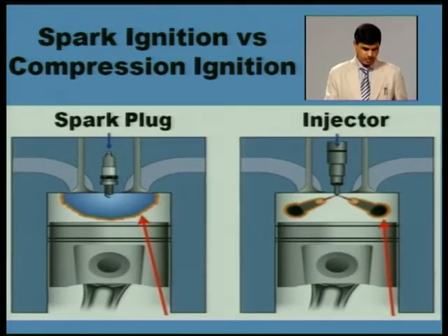In the case of petrol engine, compression ratio starts from say 8.5, even it can reach up to 15. But in the case of diesel engine, it starts from 15 itself. So the lowest compression ratio normally which we are getting in the engine is around 15. But maximum compression ratios these days in some of the vehicles, it is even 25. So here compression ratios are quite high. Higher compression ratio means during compression stroke, when piston will be reaching TDC, the clearance volume will be very small. That's why compression ratio is higher.